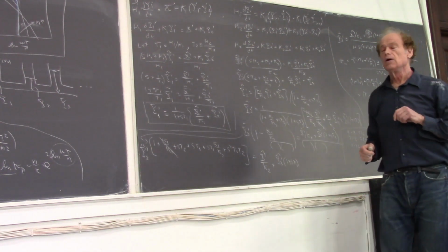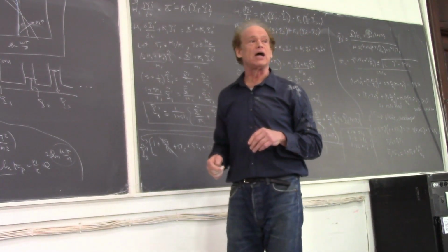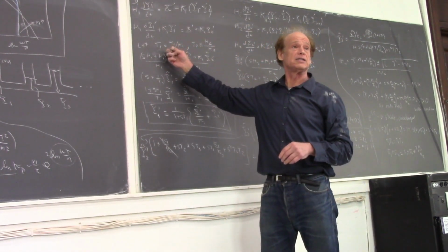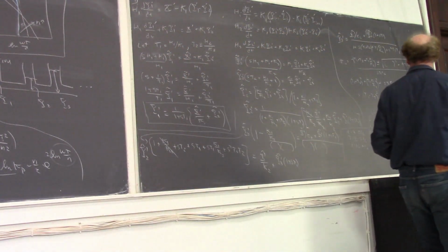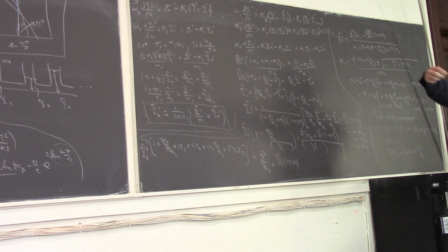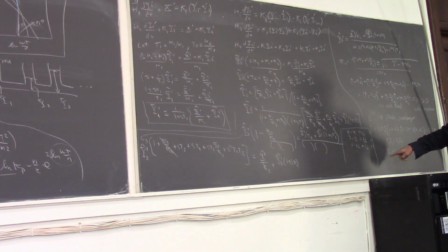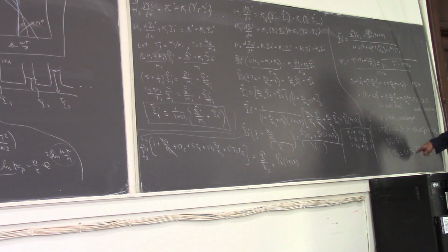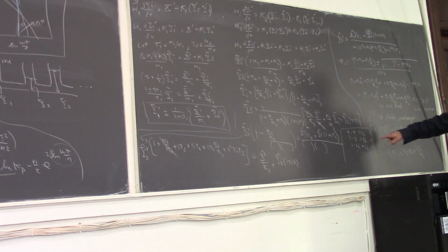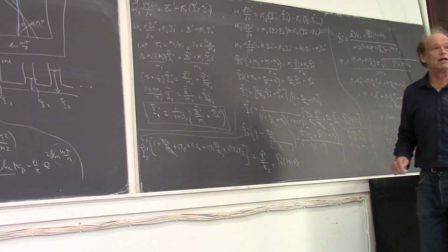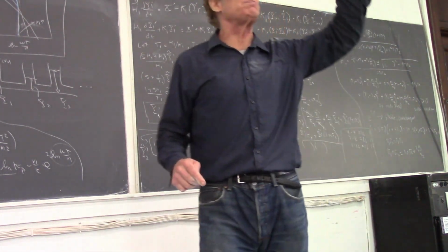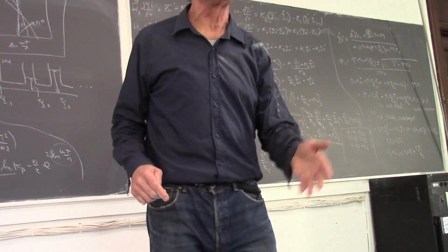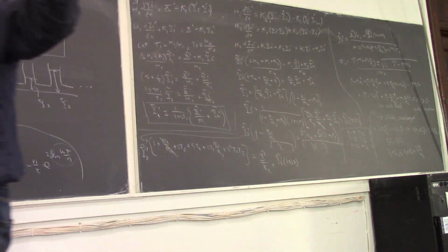T1 and T2 would be the time constants for the non-interacting system. Here, sigma 1 and sigma 2 are further apart. That is, the bigger of sigma 1, sigma 2 is bigger than T1 and T2, and the smaller is smaller than T1 and T2. So what does that tell me? That says I have one exponential decay that's really fast, and another one that takes its time.